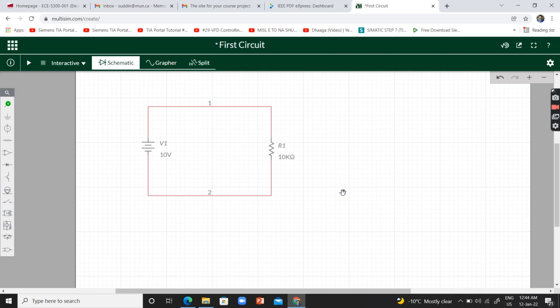The important thing in Multisim is that you need to provide a ground node in any circuit, right? So you need to specify what your ground node is. So you pick the ground, and you know that your return node is the ground node, which we normally did in the basic circuit analysis course of nodal mesh analysis, right? So I'll place this over here because if you don't specify the ground, it won't complete the simulation, right?